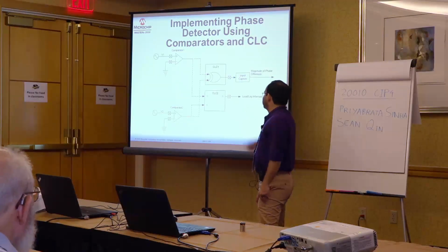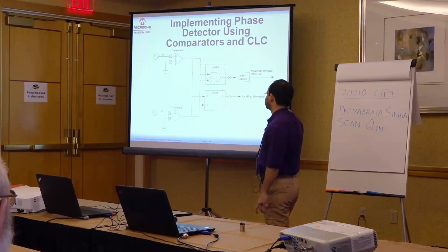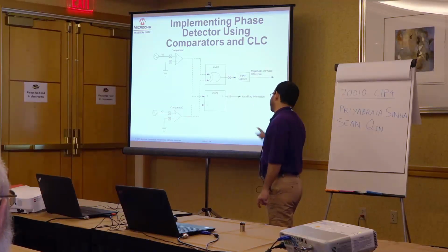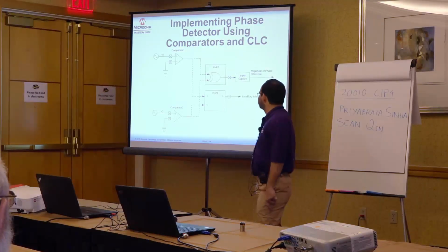And then the second CLC module is used in a D flip-flop configuration. So, you feed one signal as the D input, the other one as the clock, and you get the lead-lag information.